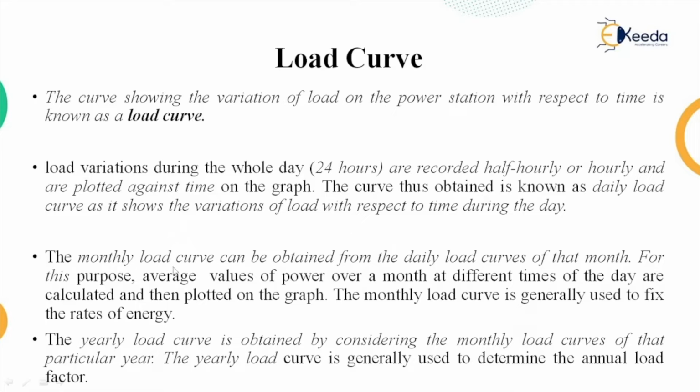Next, the monthly load curve. The monthly load curve can be obtained from the average of the daily load curves of that month. Suppose we have to calculate the load curve of December 2021. Then we have to take the average of all the days from 1st December to 31st December of 2021, and if we take the average, we get the monthly load curve.